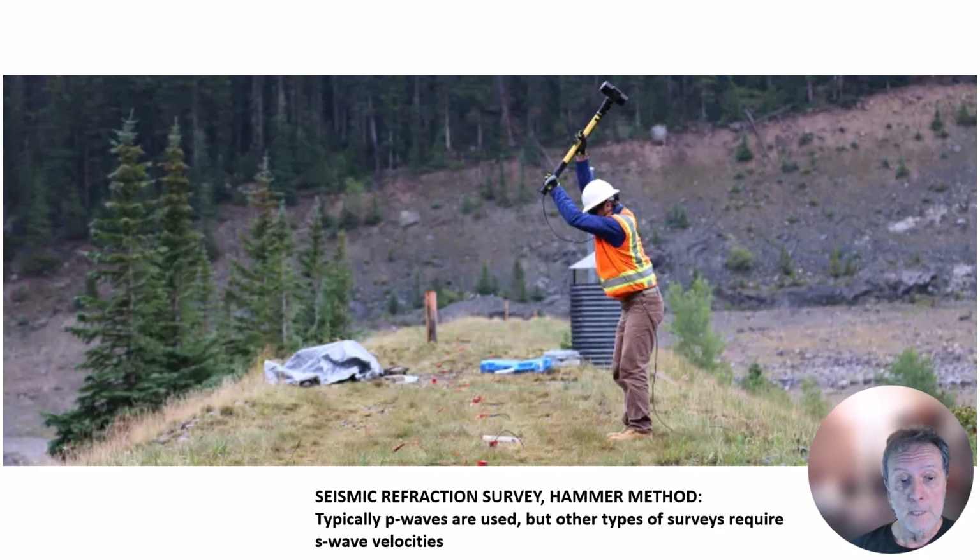So we're talking mainly about soils, and I'll talk a little bit about hard rock investigation. Hard rock investigation obviously involves material of much denser quality. We often use seismic or geophysical methods to determine relative density of bedrock and conduct rippability studies. So rippability studies are used to determine whether you can rip a rock mass with a bulldozer or whether you have to blast it with dynamite or some other explosives.